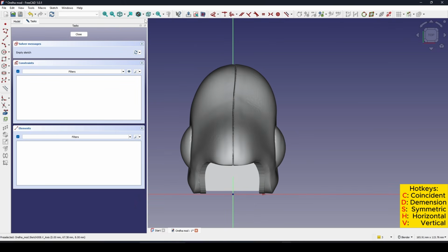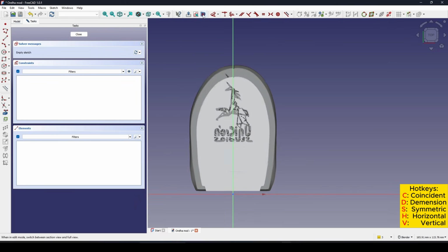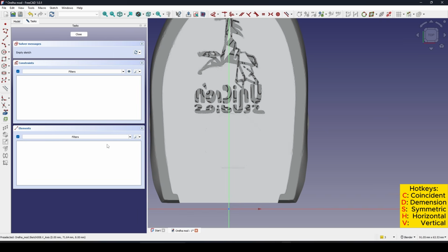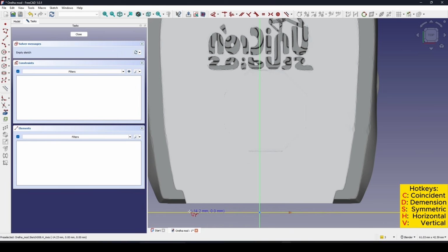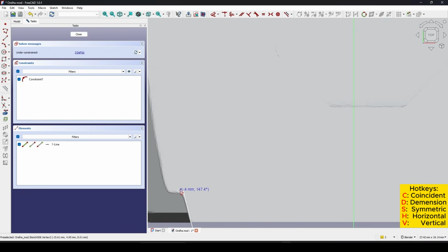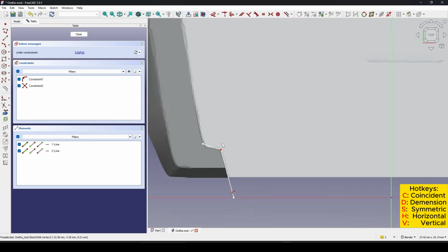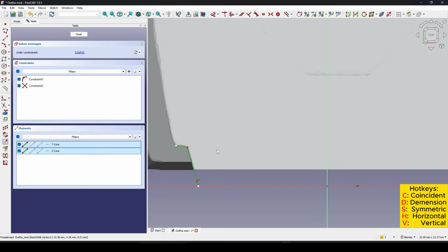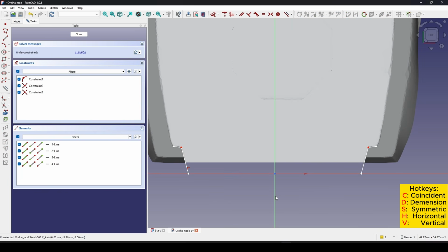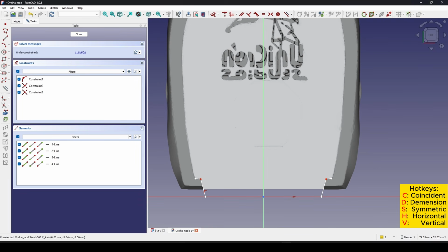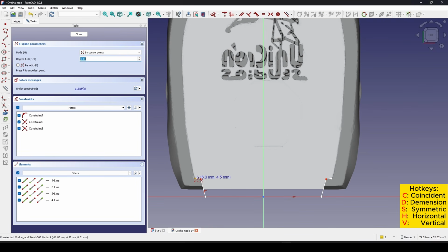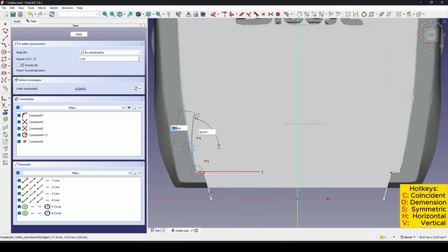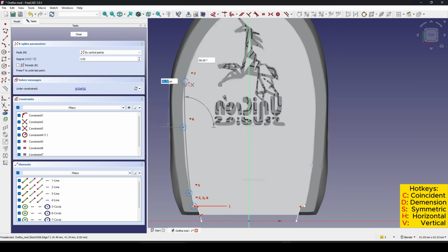Let's view the as is and view the section. Now I'm going to create a polyline. Let's start from here. Select this and go to the symmetry in the y-axis. Now I'm going to go to the B-spline and start to trace the outline of the inner geometry.